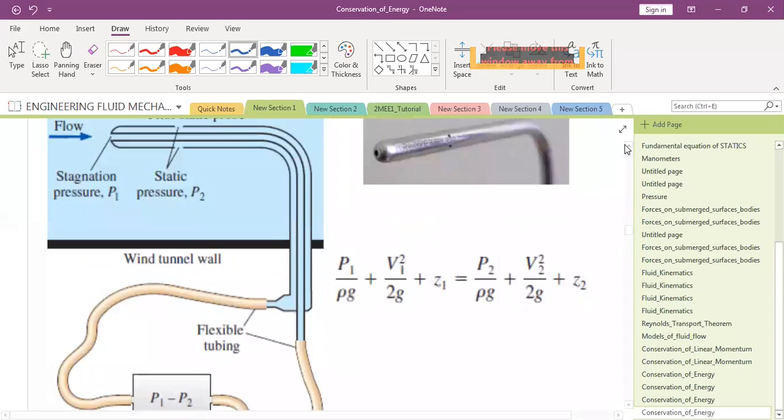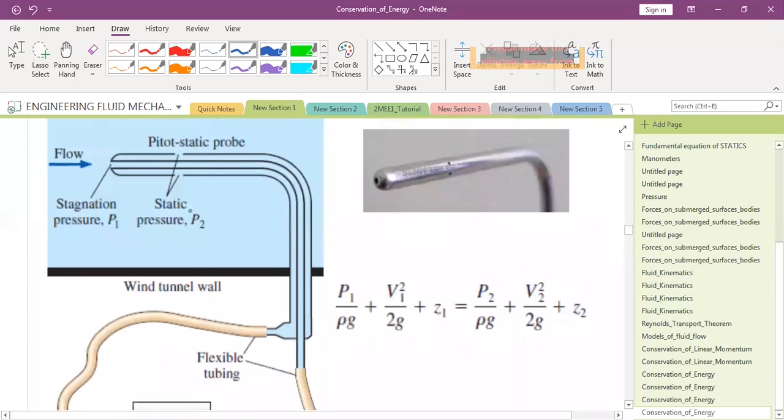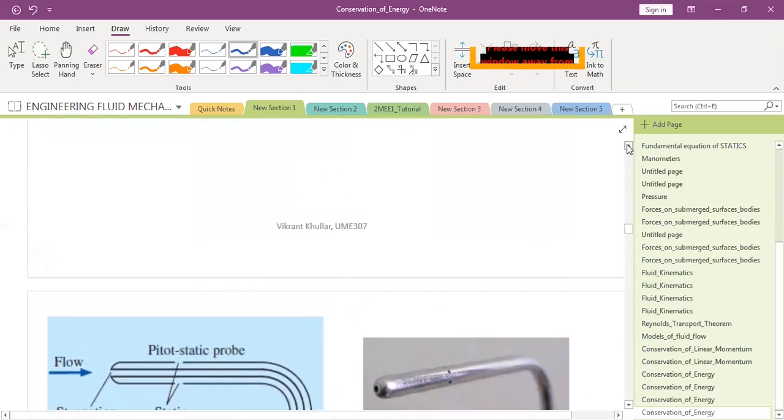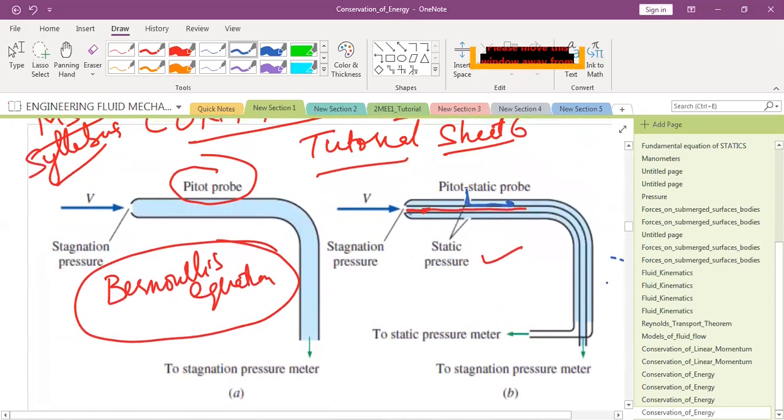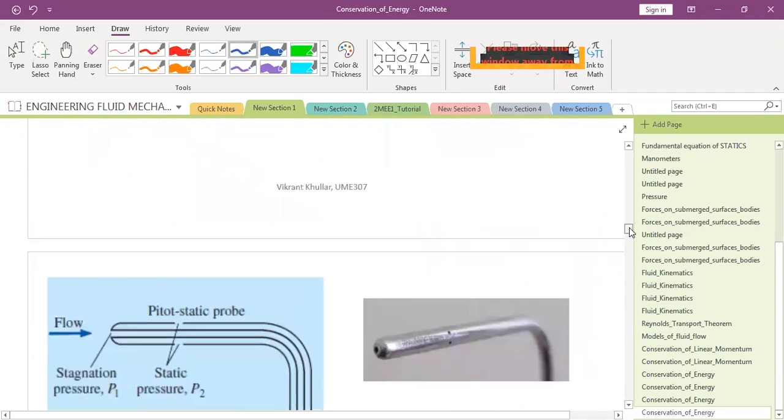This is a better example which will help you to understand which one is measuring which. So I have got one answer. Red will measure the total pressure and blue will measure the static head. So this was red, that is, fluid will get stagnant and whatever you measure is the total pressure, whereas these are measuring static pressures.